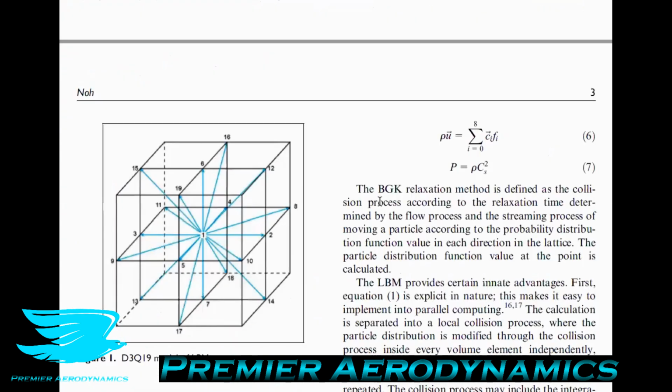They say that the Lattice Boltzmann method is a different kind of CFD tool compared to the classical CFD methods, such as Reynolds-averaged Navier-Stokes, large eddy simulation, and direct numerical simulation. So these are all Navier-Stokes based CFD approaches: RANS, URANS, DES, DDES, IDDES, LES, DNS. And they say it does not depend on the discretization of the Navier-Stokes equations, but rather on the statistical distribution of particles in a given fluid and their interaction based on the Lattice Boltzmann equation, which is derived from the original equation proposed by Boltzmann in 1872.